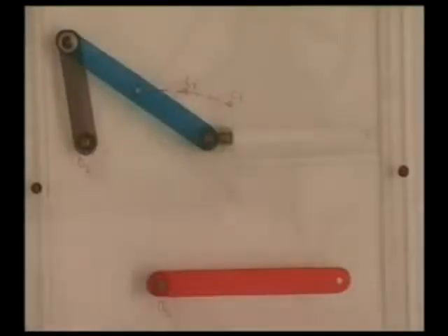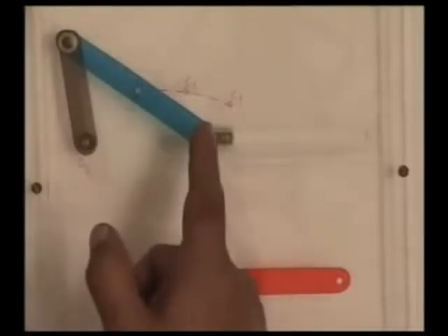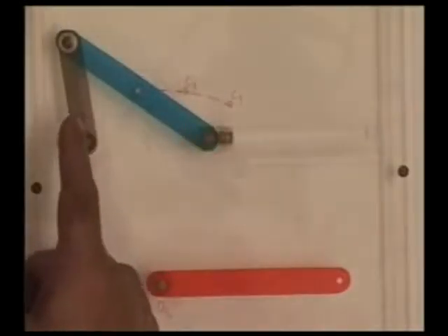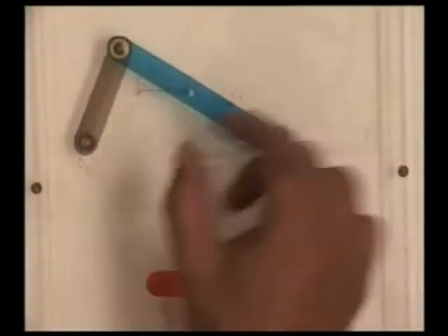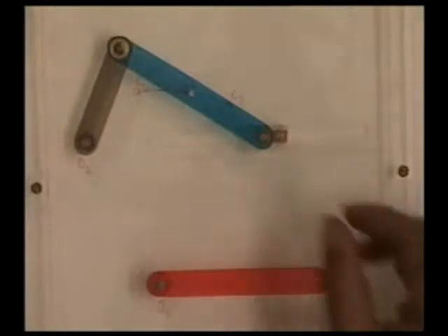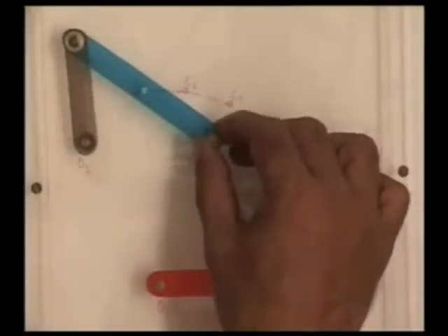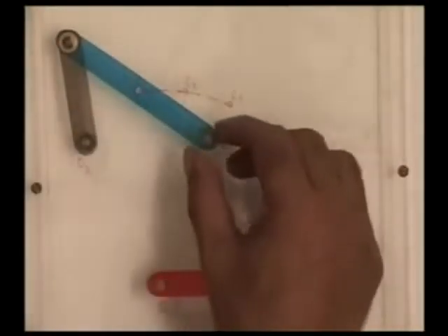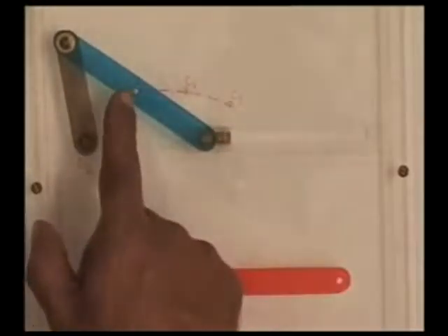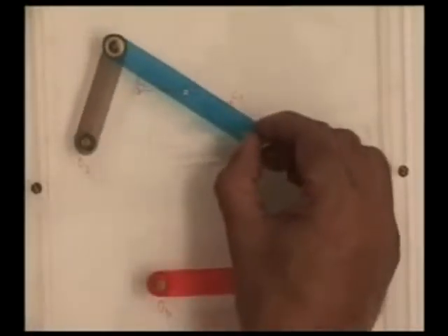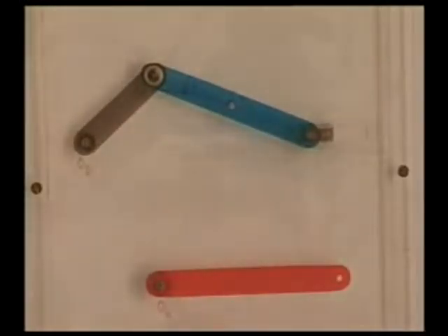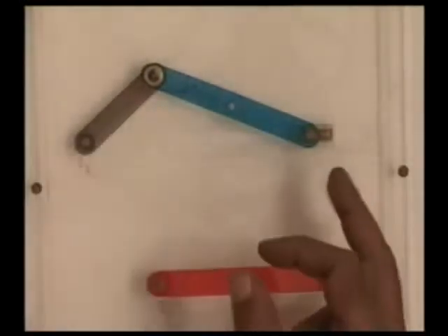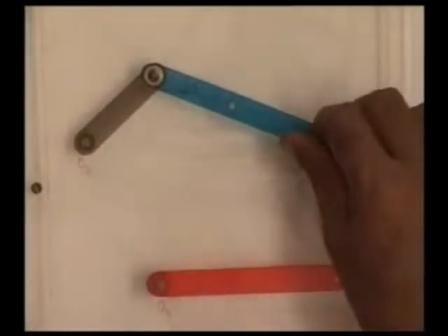Let me now repeat this two-stage synthesis problem. What we did, first we designed a slider crank mechanism such that it acted as a function generator. The slider displacement was coordinated with the crank rotation. Then we took the midpoint of this connecting rod at these three configurations, which is C1, C2 and C3, for the three positions which have been generated by this slider crank as a function generator.